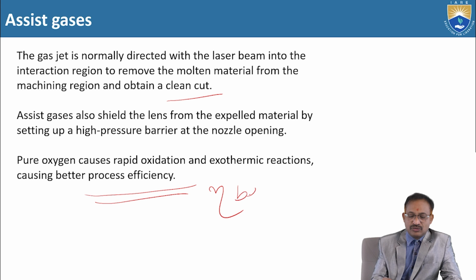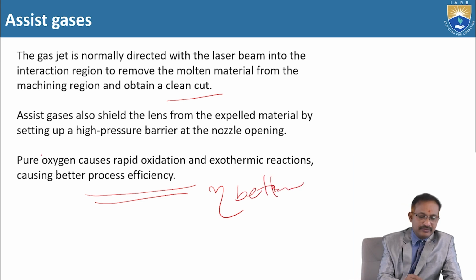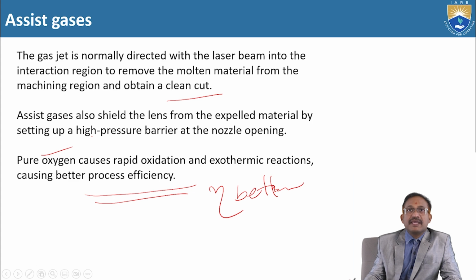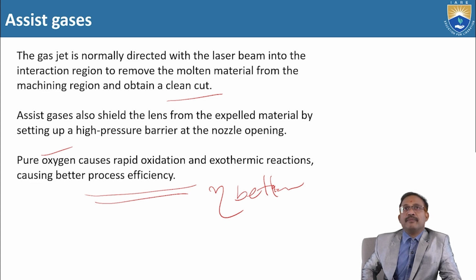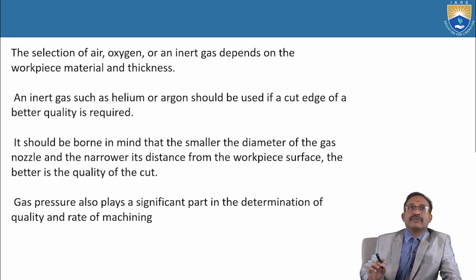Pure oxygen causes rapid oxidation and exothermic reactions, causing better process efficiency. So that is the role of assist gas in the quality of the drilled hole.